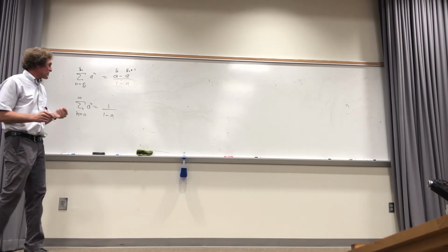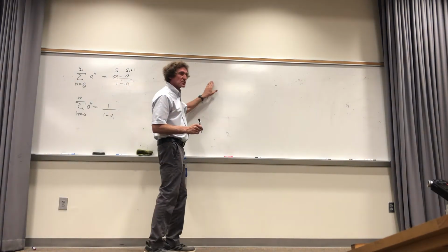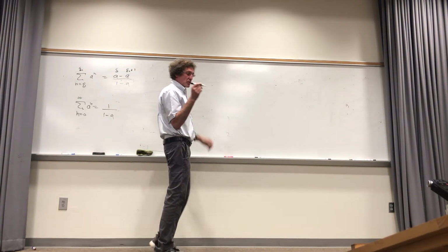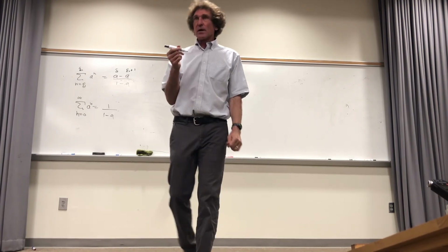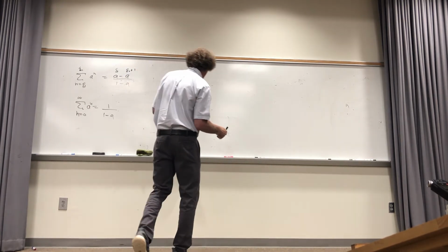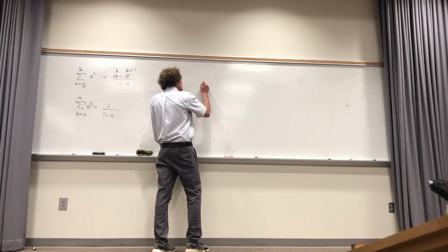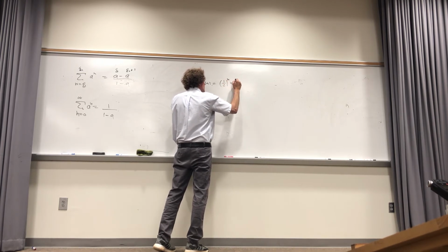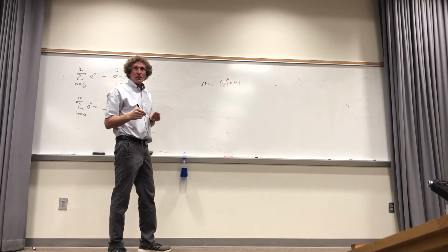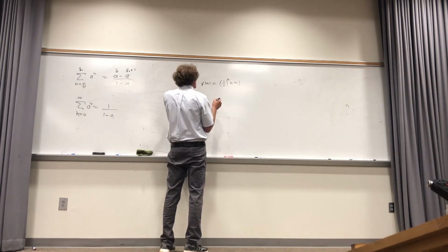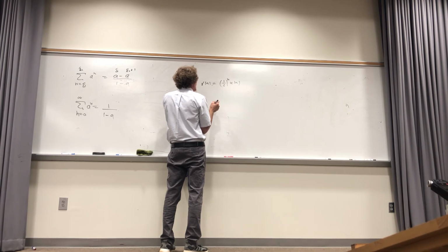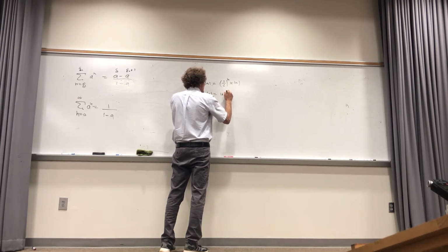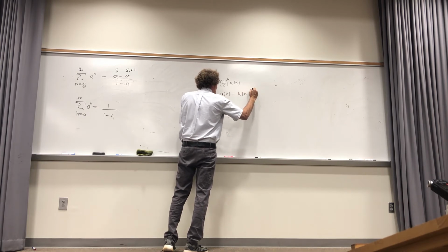So for discrete convolution, at least, suppose I give you a simple discrete convolution problem. We could do it with either finite or infinite domain functions. If I have x of n equal to 1/2 to the n u of n, and I would convolve that with, say, h of n equals u of n minus u of n minus 3. Are you with me?